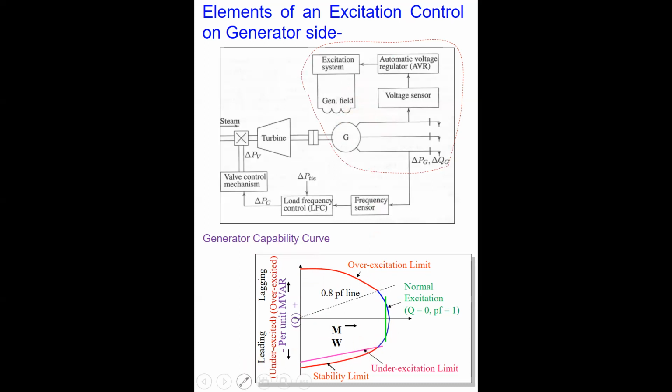Now, as shown on this curve, to illustrate here, if I say the generator power factor is 0.8 lagging, it will be this much amount of active power and this much amount of reactive power. So with the 0.8 power factor lagging, this is the active power, and this is the lagging reactive power supplied by your generator here.